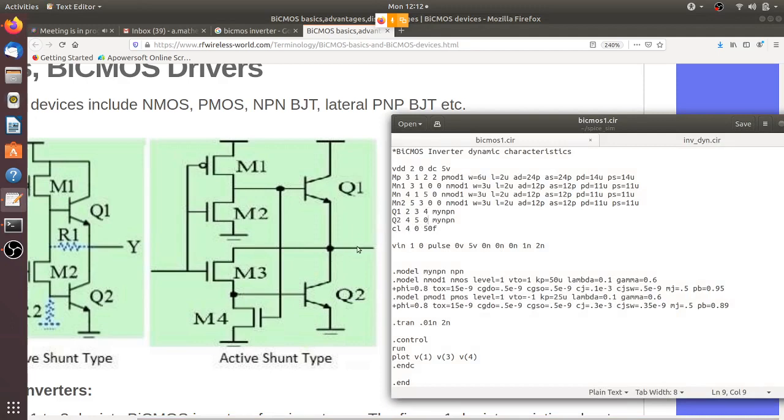And then I am connecting a load capacitor, the same as I showed in the other program, which is the normal CMOS inverter. I put 50 femtofarad there. Here also I am putting 50 femtofarad as the load capacitor. That depends mainly upon the next stage gate capacitance, and also this node has some capacitance which you have already learned about. So now let us simulate this.